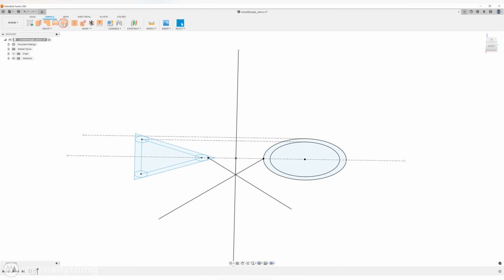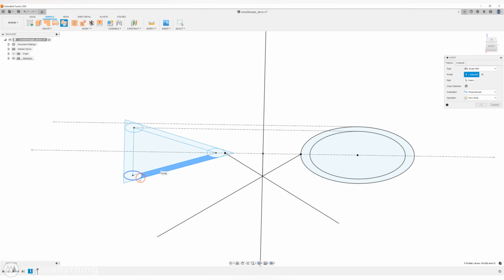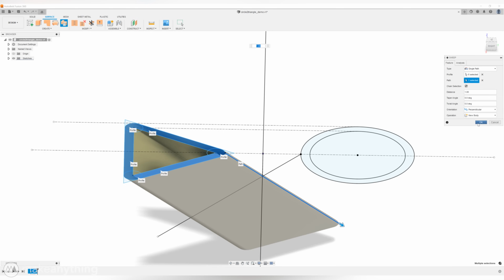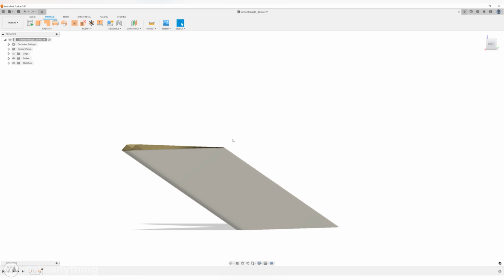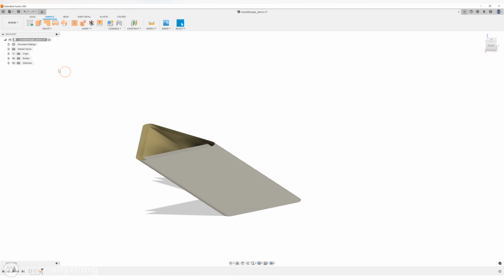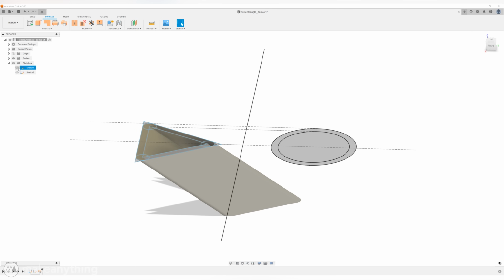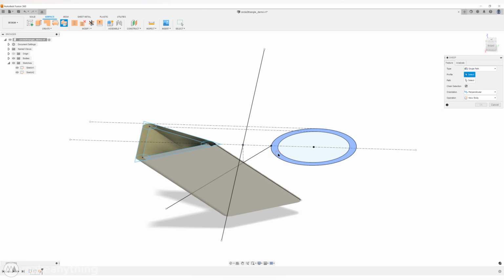We'll start by selecting the Sweep tool, and then highlighting all the parts of our triangle, making sure to exclude those pointy corners. Then we'll click over here to select our path, and click this diagonal line to build a surface for the inner and outer profiles of our triangle. Now open up the sketch tree on the left here so we can turn both those sketches back on, because we want to do the same thing in the opposite direction with our circle profiles.